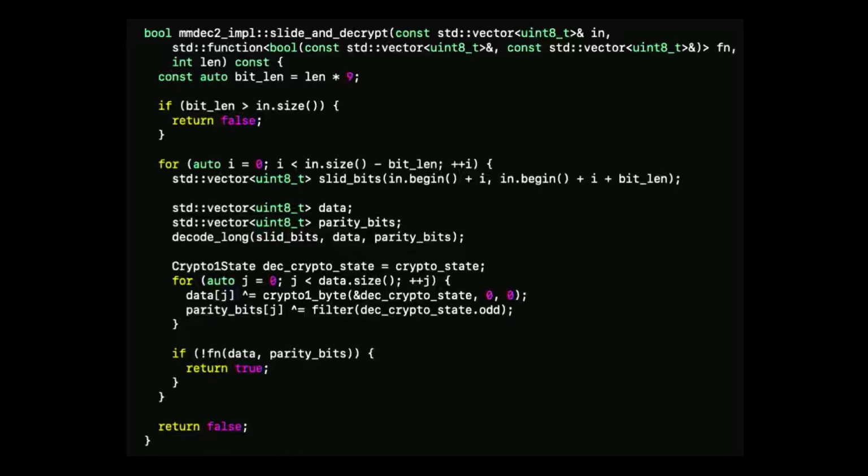And we can also take advantage of an offline attack. Normally readers have to be quick, they have to try and figure out what your card said very fast, because otherwise you're waiting there holding your card. We can do offline attacks: we can sniff traffic and then spend longer trying to resolve any errors in the RFID signal. So what this does, for example, is flip all the bits in a bunch of various patterns, trying to fix all the parity, for example.